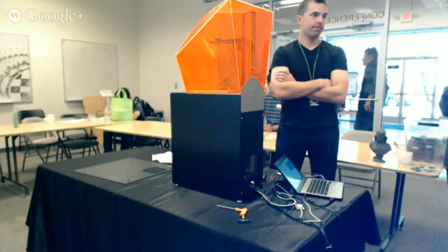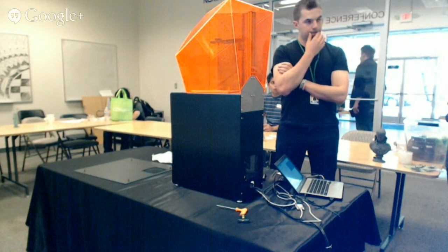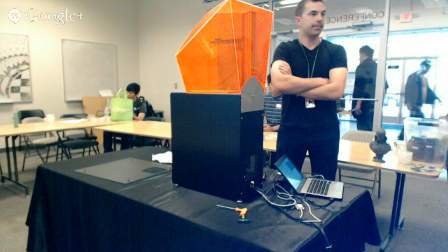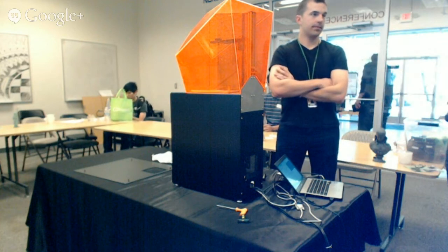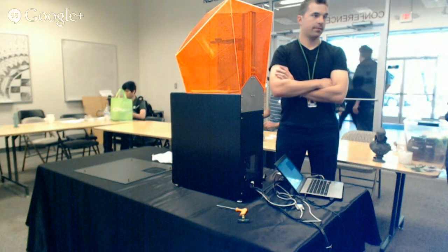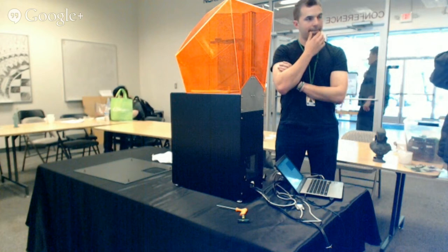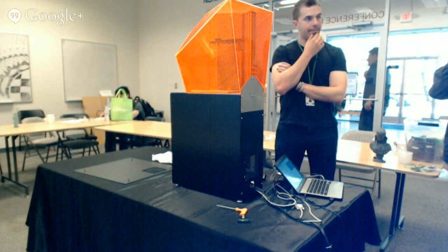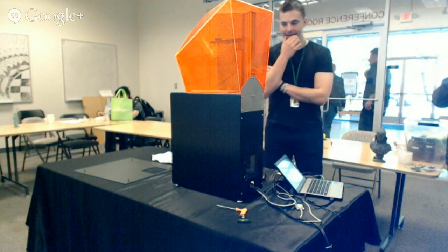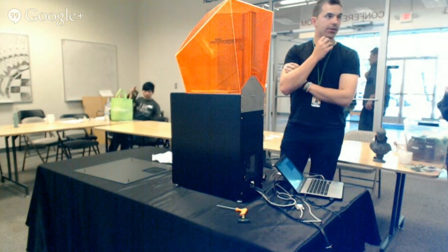The Stratasys material, for FDM even, is designed to be run at a specific temperature, a specific way inside of that climate-controlled build, so that you get extremely repeatable results. And those parts, their ABS does not shrink. None of this 10% shrinkage, whatever. That stuff doesn't shrink. It's wicked expensive, right? But compared to all the variables that we have here, many of these variables have been eliminated in the high-end printers. That's in reality what you're getting with the $20,000 to hundreds of thousands of dollars printer.